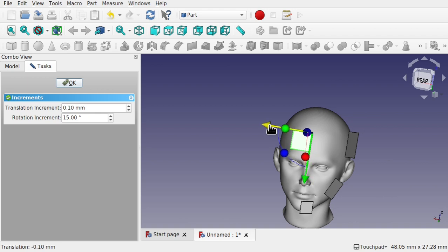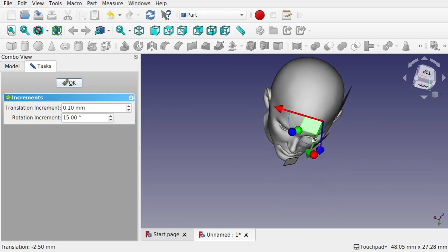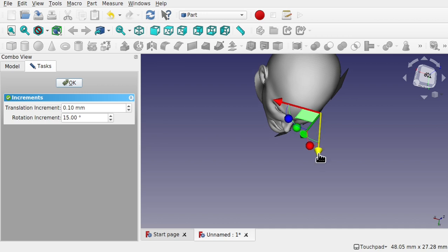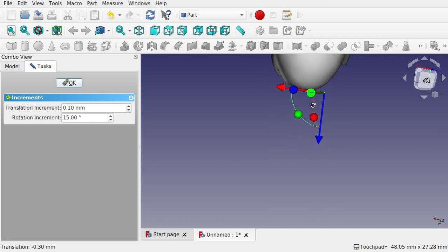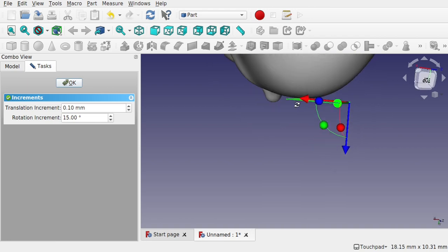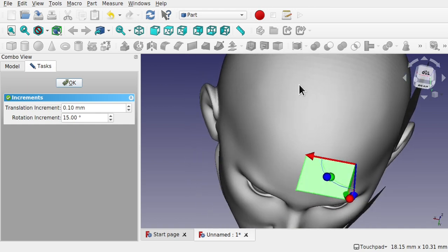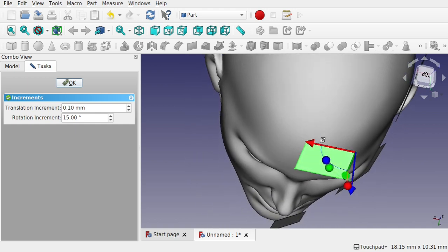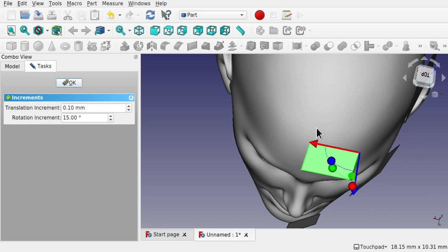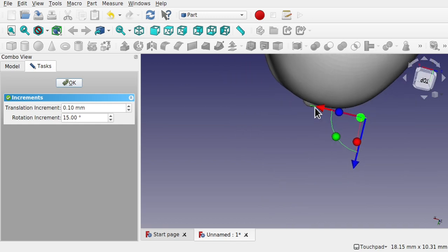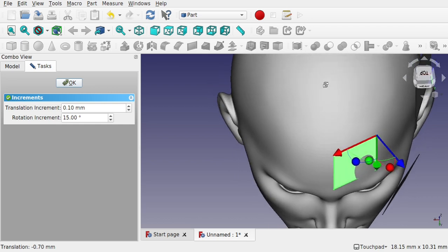And remember, we're looking at lining one of the edges up, around about there. And we're more focused on the edge that we're going to create the curved surface from. So I'm going to create it from this line here. And I've used this plane to angle it, because the plane will make the angle. So let's angle it correctly. Push it on, push it back. Have a look.